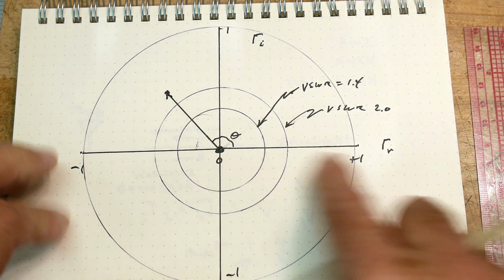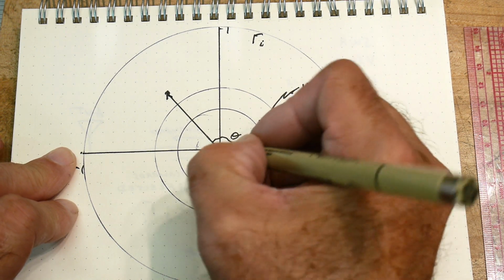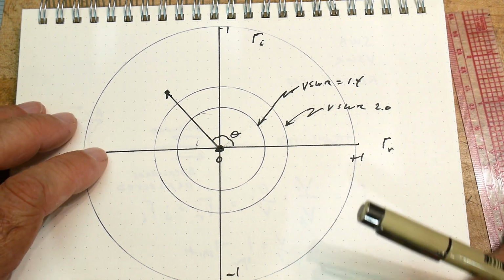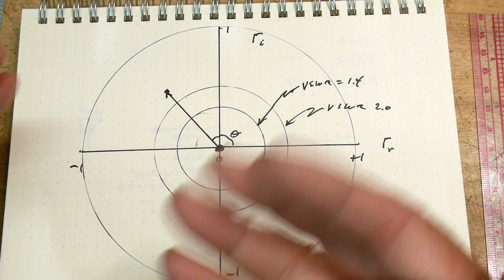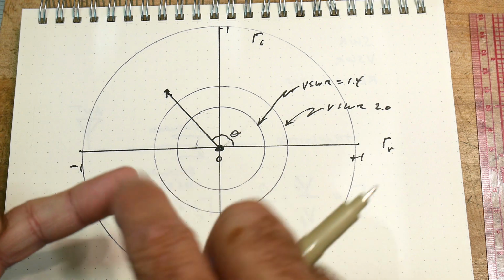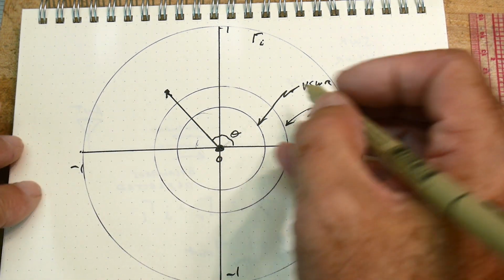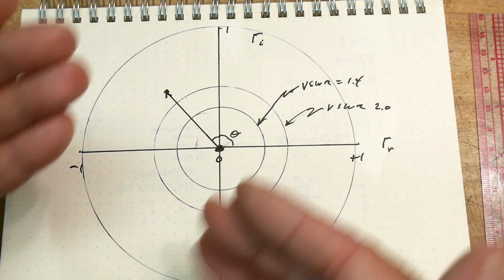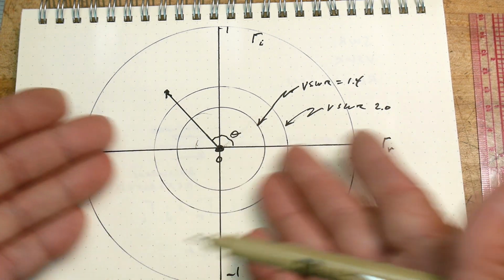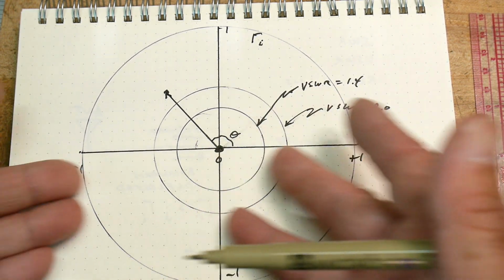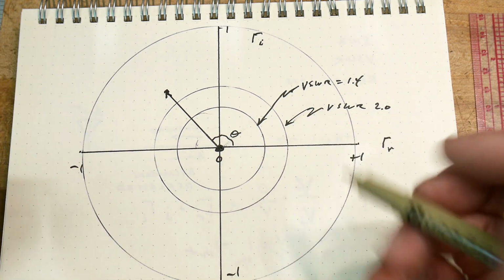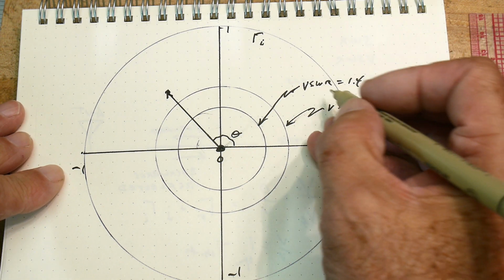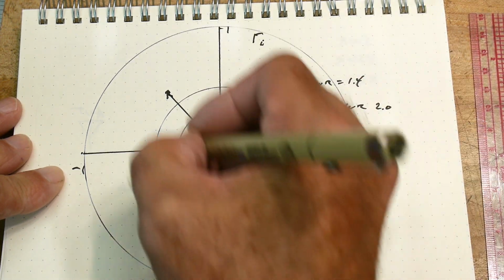They can go from plus and minus 1, and goodness is in the center. And if you understand that there's complexity, there's complex numbers, which means that there's phase information, then you can have an SWR of 1.4 that can go all the way around the circle because the phase can change, right? The standing wave can move back and forth depending on the frequency, and you can move around in a circle due to these phase shifts and stuff. And so constant SWRs are on these circles, okay?